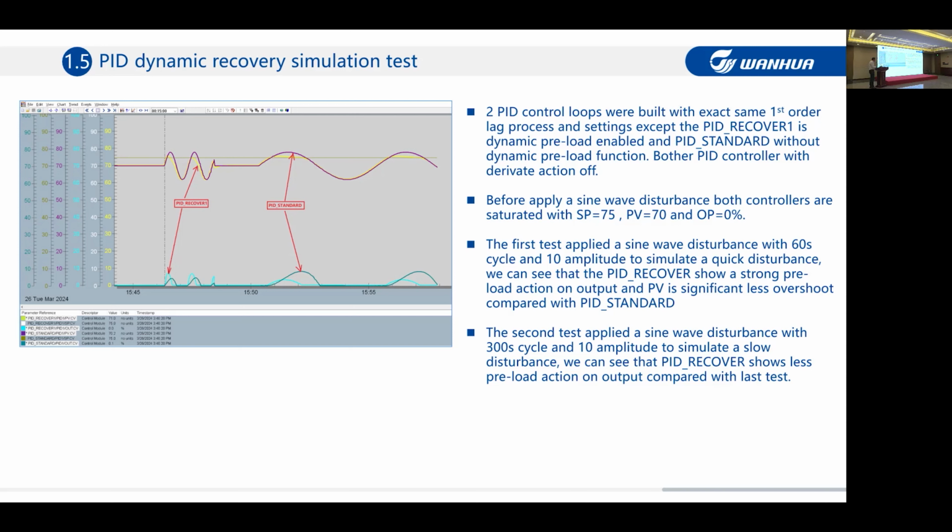That's what we want. We don't want slow PV changes or small disturbance changes to cause the valve to move. So obviously it satisfies our requirement.